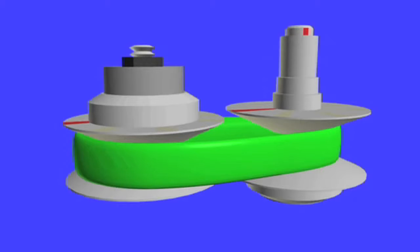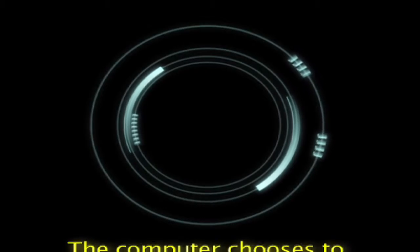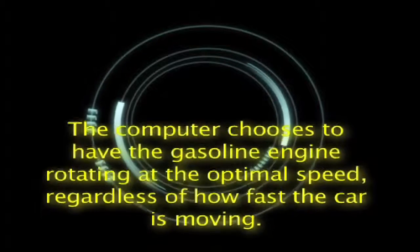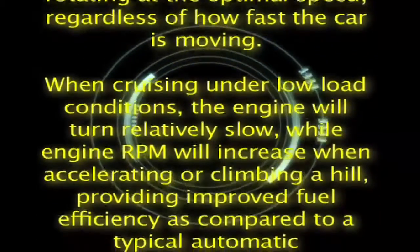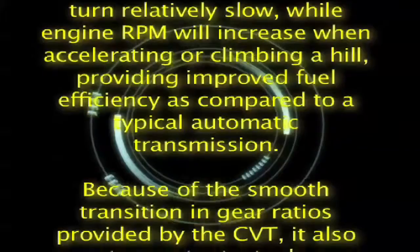By changing the width or space between the pulleys, an infinite number of ratios can be established. This is more or less the same principle as a multi-speed bicycle, where different diameter chain sprockets are selected to gain different speed ratios. The computer chooses to have the gasoline engine rotating at the optimal speed, regardless of how fast the car is moving. When cruising under low-load conditions, the engine will turn relatively slow, while engine RPM will increase when accelerating or climbing a hill, providing improved fuel efficiency as compared to a typical automatic transmission.